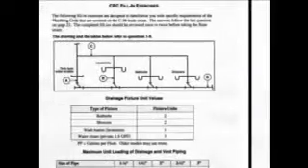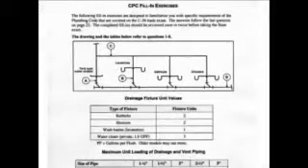Next question, number 5. The total number of fixture units at C is, and let's take a look and see where C is. C is up toward the top of the diagram, above the water closets and above the lavatories, actually between the two. It's dealing with a horizontal vent pipe, and the question is total number of fixture units that C covers.